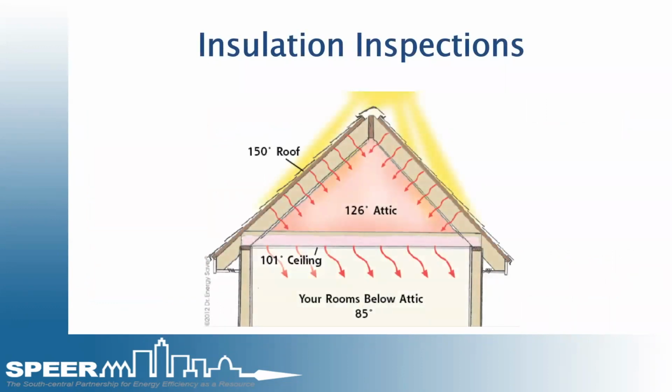So on to the insulation side of it. Just a little brief history, just kind of the way insulation works. Insulation basically works by resisting heat flow, or the transfer of heat, through the component or through the building material, either from the outside in or the inside out. Its power comes from the ability to trap air. So as long as it's fluffy and nice, it's got air pockets in there that resist heat transfer through the material. But if it's crushed, if it's compressed, if it's devoid and it's not there, then it doesn't work very good. Heat is able to transfer through more of a solid material if the pockets of air aren't there.